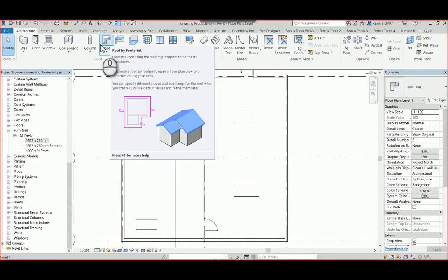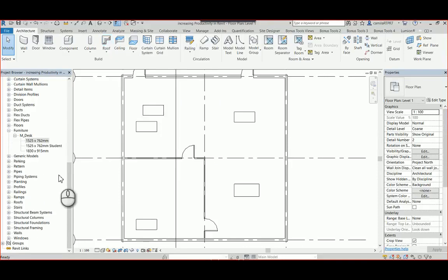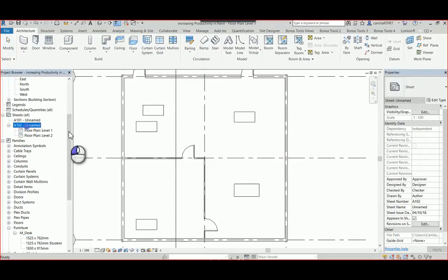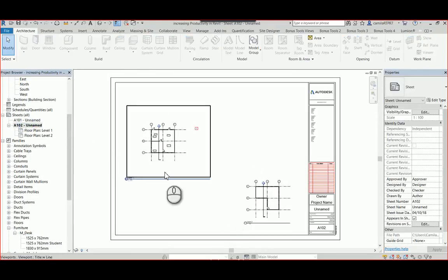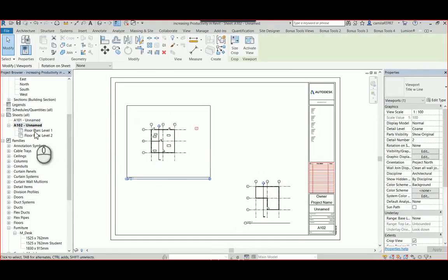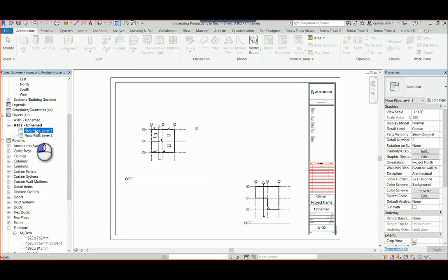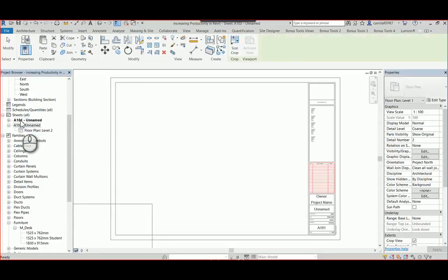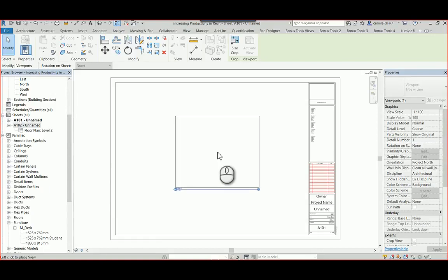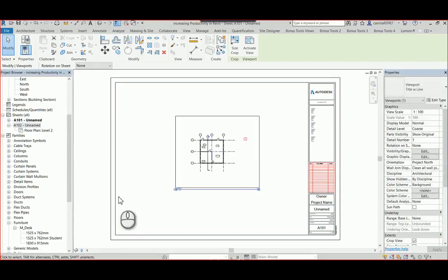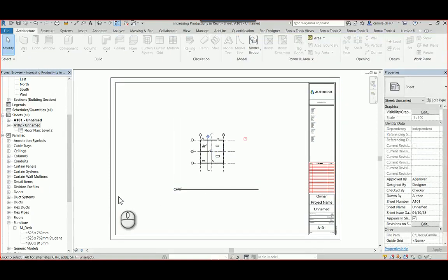My next tip is about the sheet and how to move drawings from one sheet to another. So we have here this, and let's suppose I place this one in the wrong sheet. I could delete and try to find it in my project browser, then drag and place on the right sheet. Or I can also select and drag to the desired sheet. It will be attached to my mouse. I just click to place the view. That makes your job much faster.